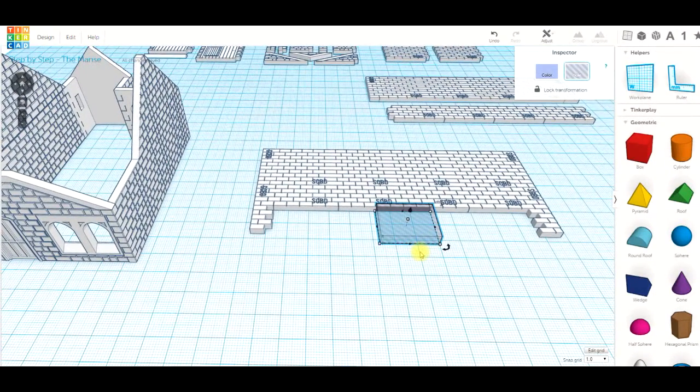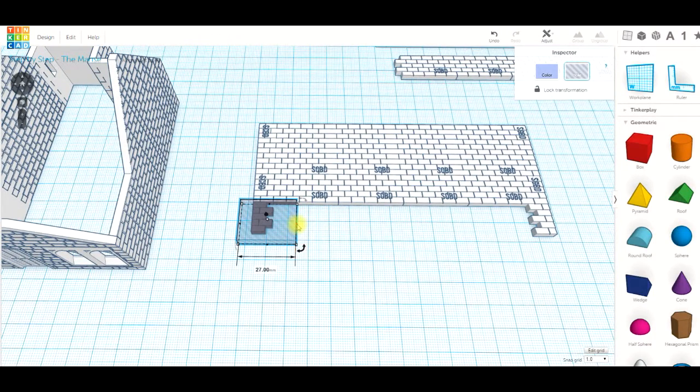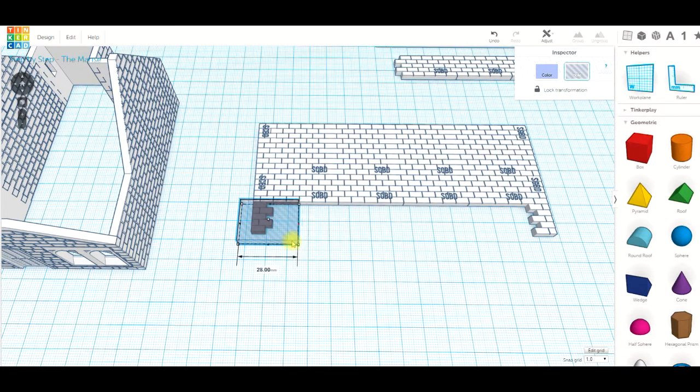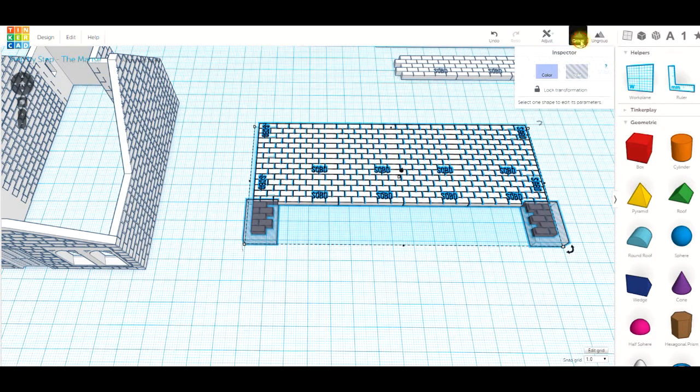Okay. Slide that transparent box until it goes over that piece. Doesn't really matter how big it is or how small it is. You could just drag that out now if you wanted to the full length. Or in my case, I'm just going to put it quite small so it fits over that edge. Then I'm going to press Ctrl and D and duplicate the clear box. Slide it over the right edge. Select everything and click Group. And those clear boxes will cut those pieces away.